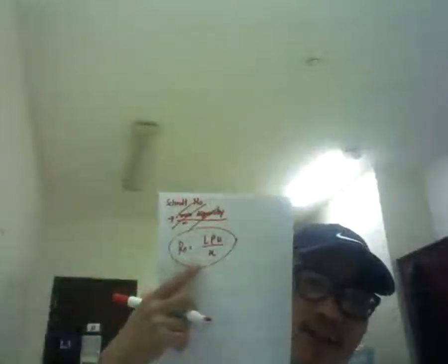So, Reynolds number, there's a basic formula I could remember: the length times the density times the velocity over the absolute viscosity, or dynamic viscosity. This is the absolute viscosity, not the kinematic viscosity.